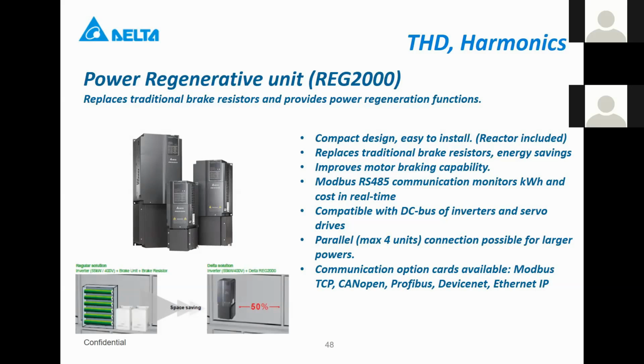Our REC 2000 has a built-in reactor. Otherwise, you cannot connect it directly to the main supply. But the current, what's coming out in the direction of your main supply is not sine wave form. So you create the disturbance already on your main supply together with the drive. But because you are using it in combination with a frequency drive, the total harmonic distortion will go down a little bit.